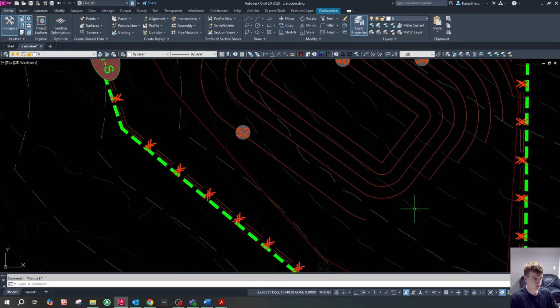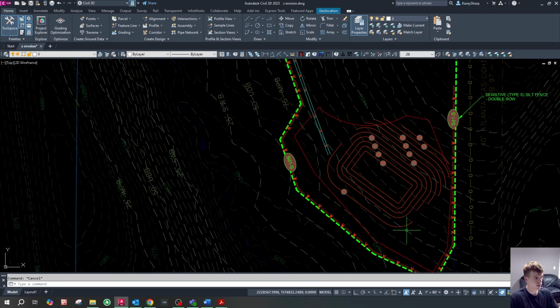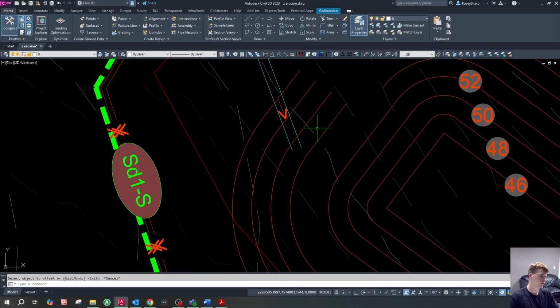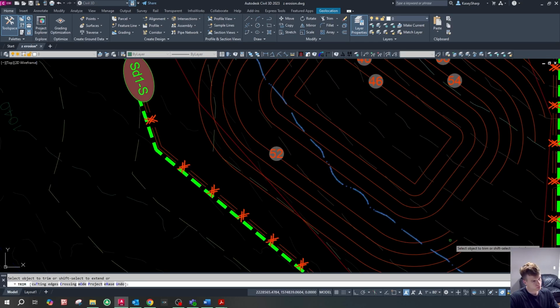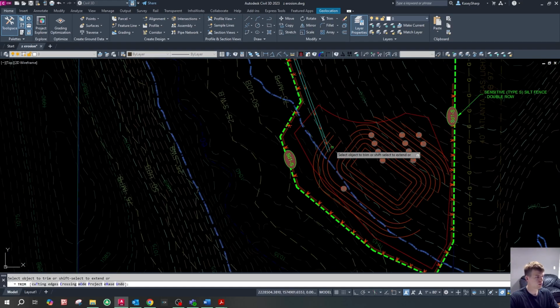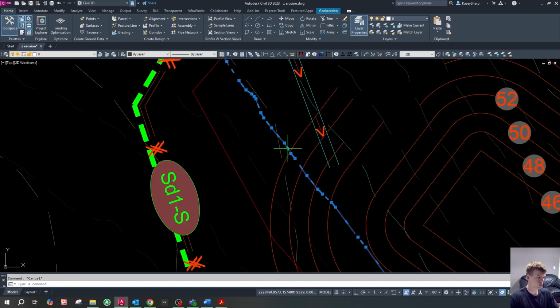So that guy's gonna have to tie in. So I'm just gonna click that and then click extend. Now we can offset from 4 feet back down. So there's the 50, the 48, the 46. Okay, so the 50, we're gonna trim off. Same thing with the 48. Trim that off. My CAD's gonna freeze because I drug the trim cursor around. We'll again trim that guy off for the 48. And then the 46 here, can trim that guy, delete that.